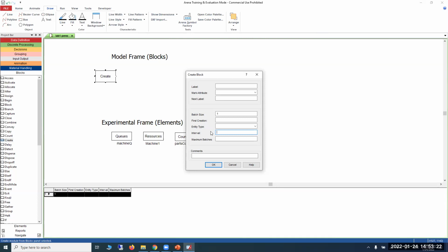But since we know that there's uncertainty in the arrivals, in the processing time, and so on, that's why we are using simulation, because we cannot solve those type of models by hand or using equations. We need computer models to help us understand the impact of the uncertainty in the system. And that's why we are using probability distributions to represent the inter-arrival times and also the processing times in the machines.